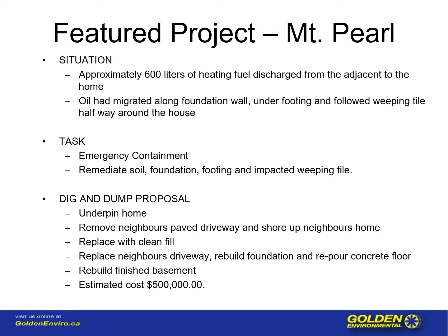Our next featured project was in Mount Pearl, Newfoundland. Situation was a 600-liter heating fuel tank discharged adjacent to the home. The oil had migrated along the foundation wall, under the footing, and followed the weeping tile halfway around the house. So our task was emergency containment, then to remediate the soil, the foundation, the footing, and impacted weeping tile.